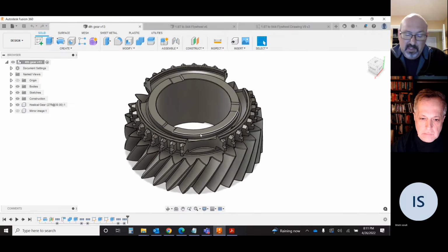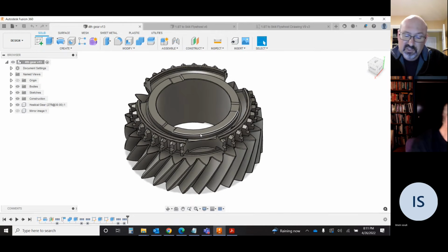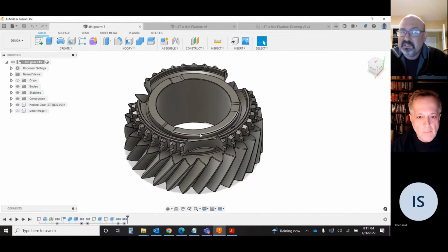But even if they have the model, there might be specific things you need to draw attention to, and that's where the 2D print or 2D drawing comes into play. Examples might be specifying a material type or calling out specific tolerances. Typically, most CNC fabrication will hold about 5/1000ths of an inch tolerance on most features in the inch system.